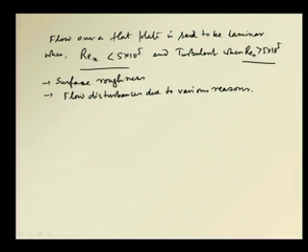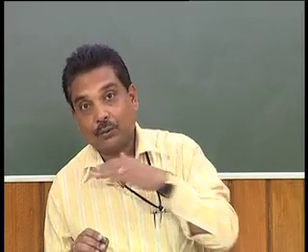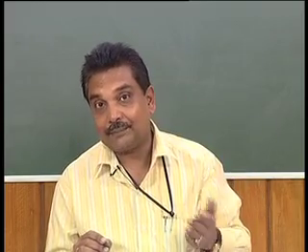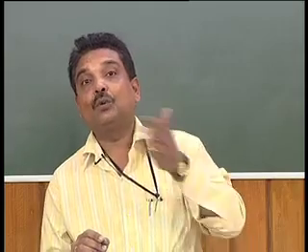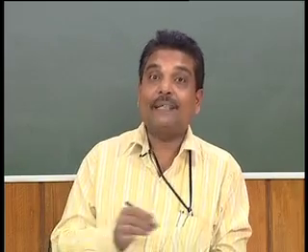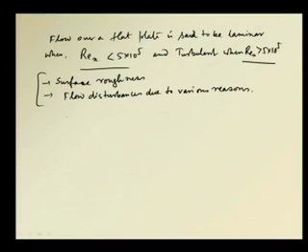So, surface roughness is also a reason for the disturbance of the flow. The more the surface roughness, the more turbulence it will give to the flow situation, so you can have an early turbulence in the flow. Therefore, it is said that when more disturbances are there, turbulence can even happen with a Reynolds number as low as 10 to the power 5.